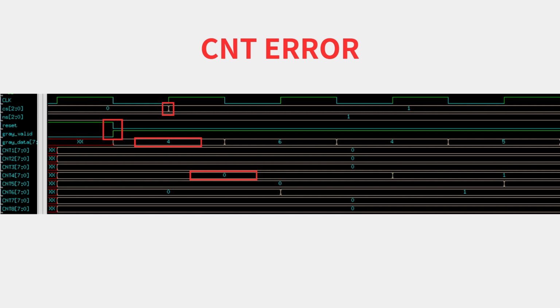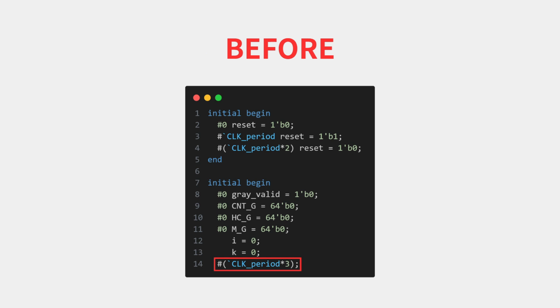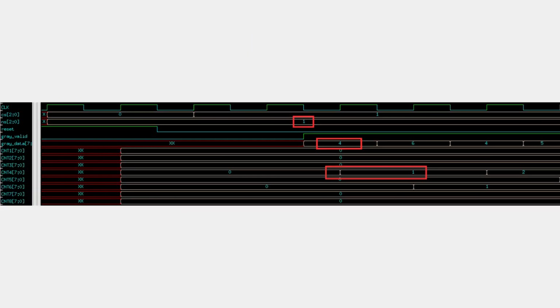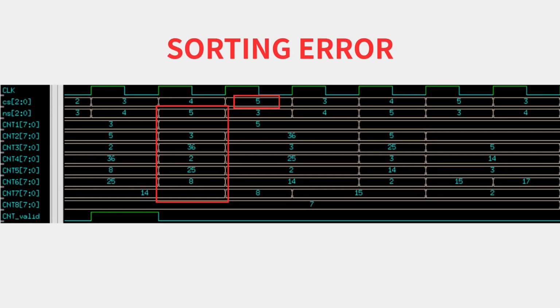This is because there's no state transition time between state idle and read, which means reset and valid input happen respectively. The solution is to postpone the time that data starts to be delivered to the circuit from a trial period of 3 to a trial period of 5. And this is done by the TA, and we get the correct waveform.